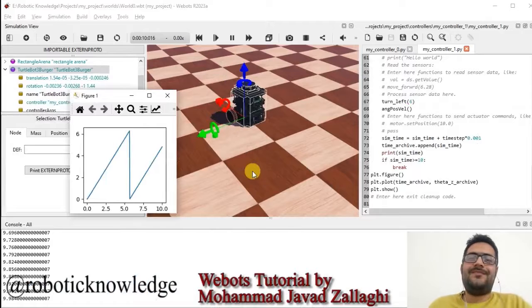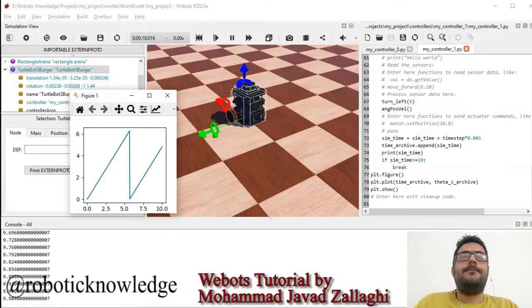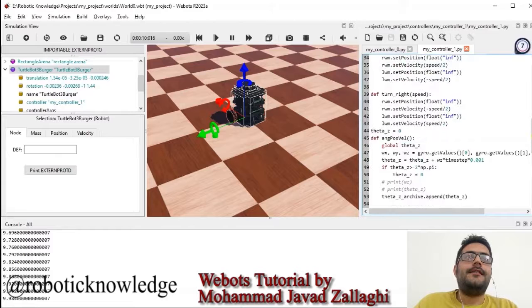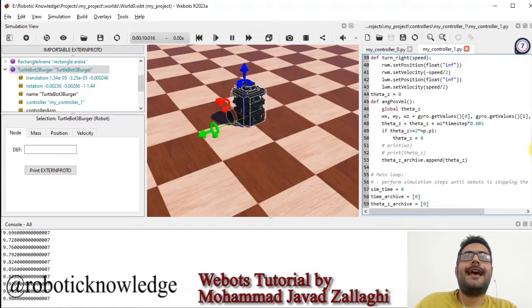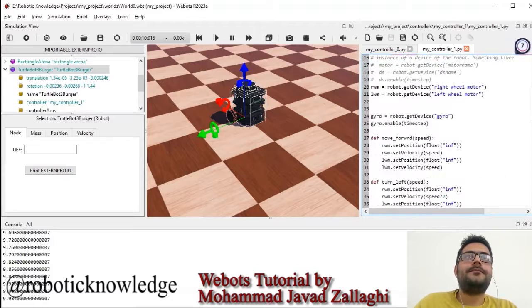In this lecture we have learned how to set up the gyro sensor in a turtlebot, how to use its measurements, and how to perform a simple numerical integrator in a function, and using that we find the capability to measure the rotational angle of a turtlebot.